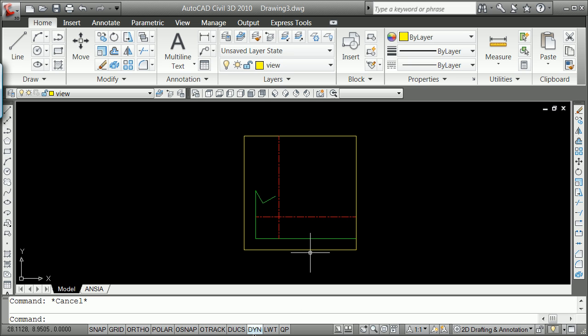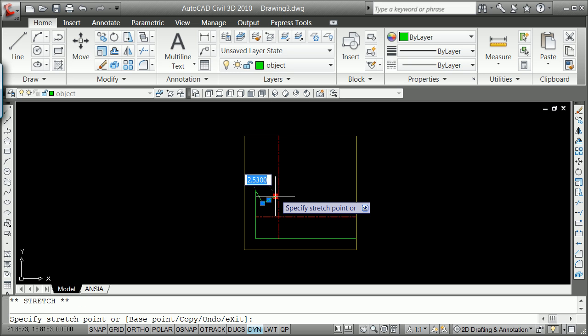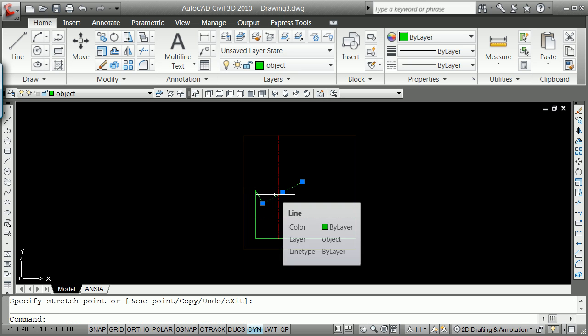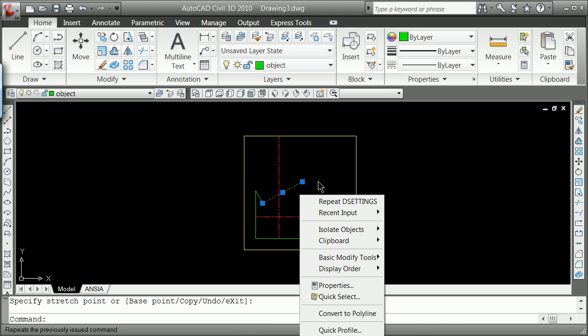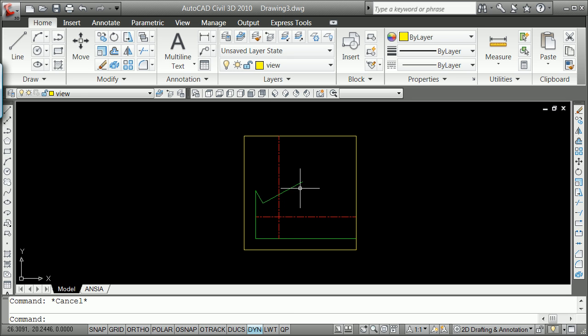Now you turn the dynamic back on, and you left click on the edge, and you now change that length to the 8.01 that it is. You can then hit escape or right click cancel or whatever works for you. You now have the second length. You turn the dynamic off. You left click, spacebar, C for copy, and you're going to turn that. It appears to be 82 degrees.